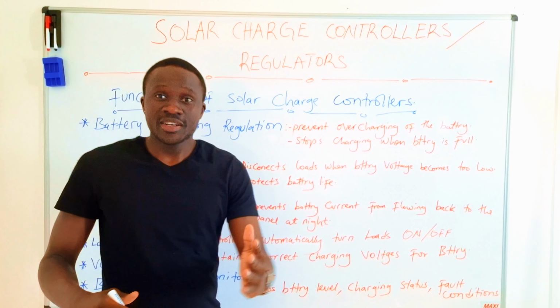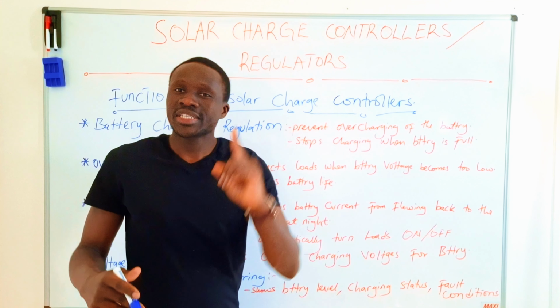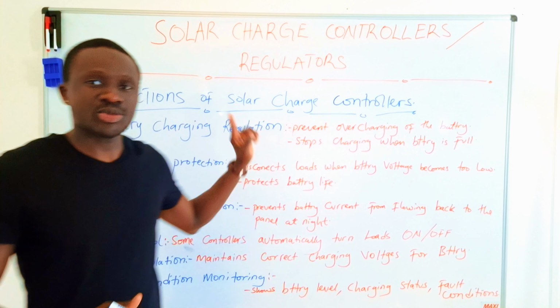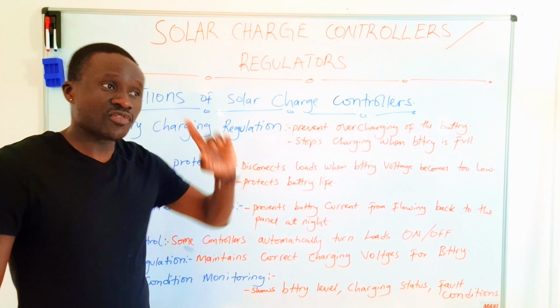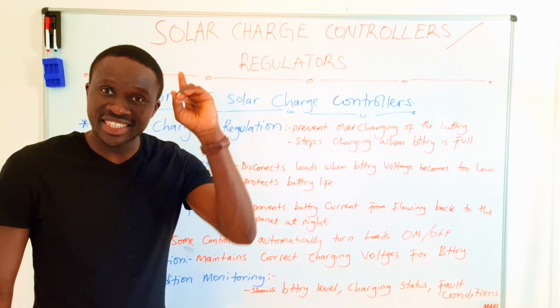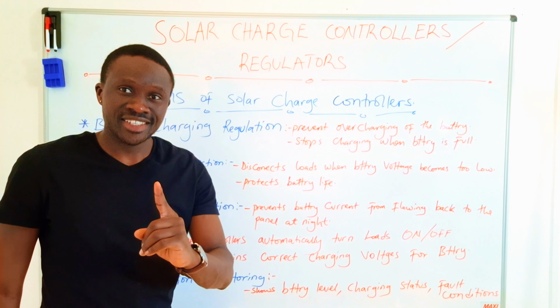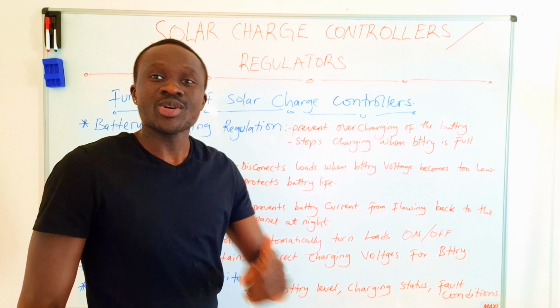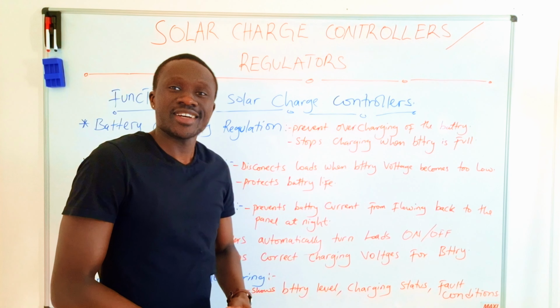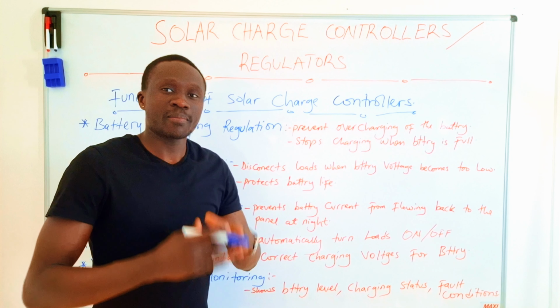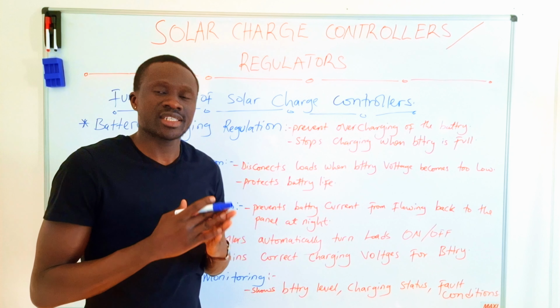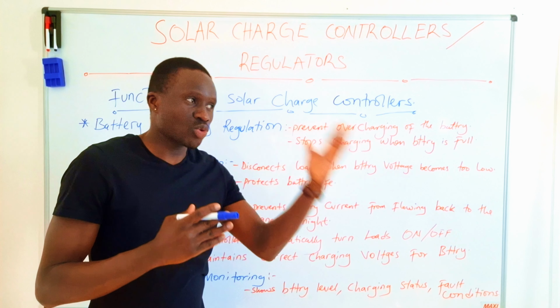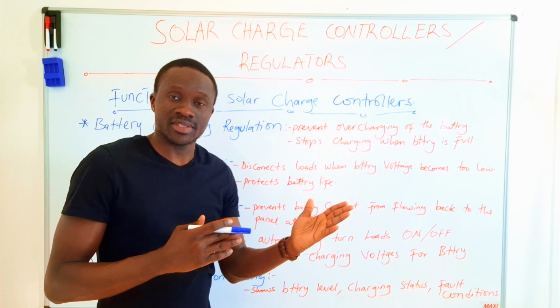If you're a technician, do not go to a customer's premises without a charge controller. If you have failed to find one, at least look for all ways to import it from another country, because your system will not achieve what we want. Our aim is to solve electrical bills.